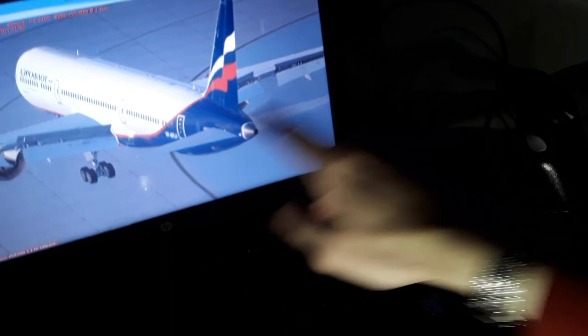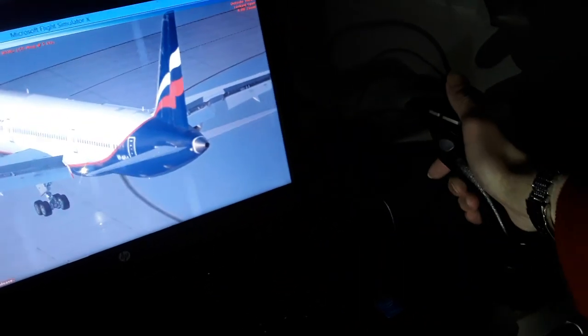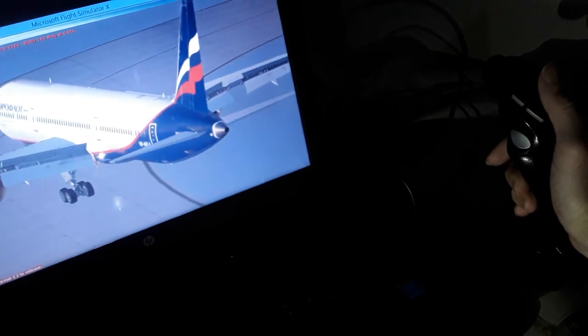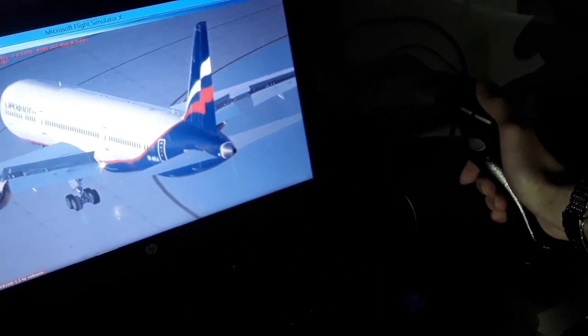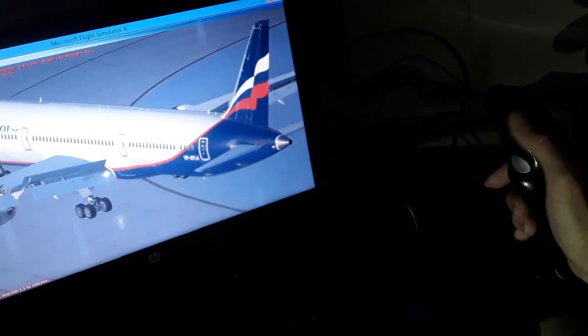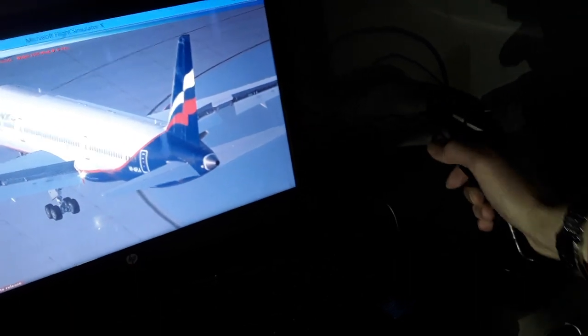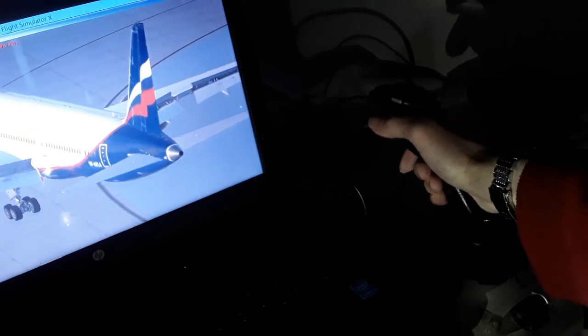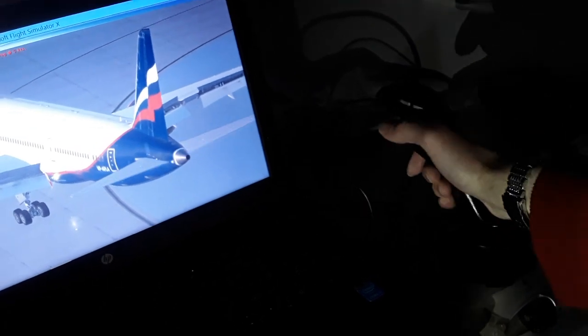So in the Airbus you use the side stick, pull up or pull down, back and forth. For climb and descent you move the elevator surface. Also we have the trim of the elevator or the horizontal stabilizer surface when we fly to balance the aircraft. Some of this trimming is automatic. We have auto trim, we don't need to do anything to trim the aircraft, but we can apply manual trims. So we climb and descend, we take the weight up and we take the weight down, very easy.